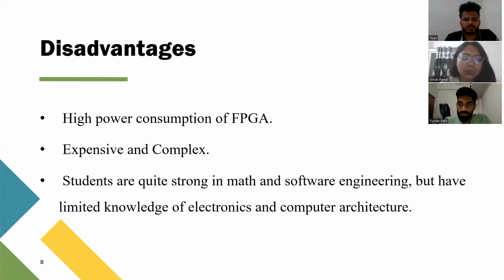Thank you, Tushar. I'll be explaining the disadvantages. So programming of FPGA requires knowledge of Verilog programming, as well as digital system fundamentals. The programming is not as simple as the C language, and everything is based on the hardware. Moreover, engineers will have to learn about the simulation tools. FPGAs consume high power, and they are expensive and complex. Also, considering that researchers are quite strong in maths and software engineering, they have limited knowledge of electronics and computer architecture. So that becomes one of the limitations. Moving on, we have the results section.